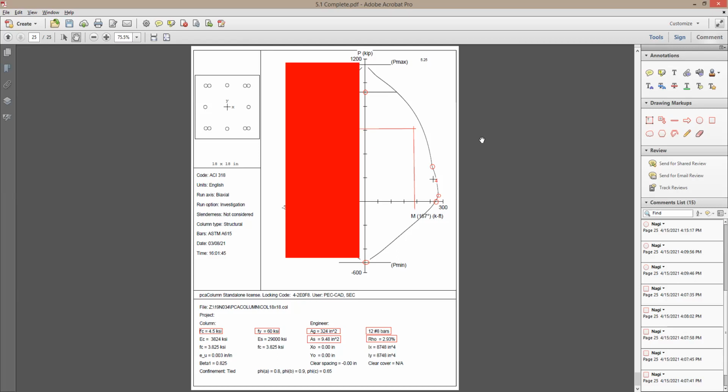So for example, if I say that this building or this column supports 10 floors and a roof, it means that you take the dead load for the floor multiplied by 10 and you take one roof, because usually in a building you're going to have a typical floor, and then at the end you're going to have one roof. In this case, you take 10 times dead load for the floor plus 1 times dead load for the roof, and then you do the same thing for the live load. And of course, at the end you multiply this by the tributary area.